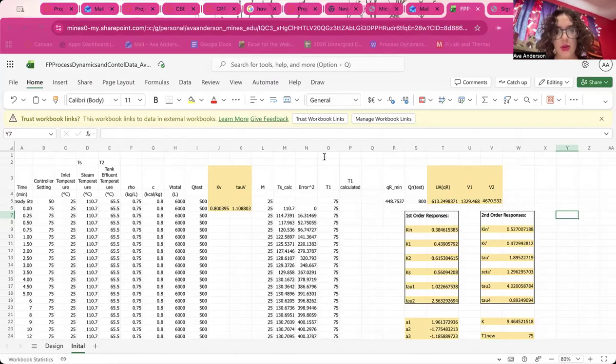The controller design was performed with Simulink. KC was found using a gain block in place of GC of S, and I manipulated the gain to see when constant oscillations were achieved. I'll show that in a second as well. The gain input became GC max, the value that I was putting in the gain block, that ended up being KC max. And PU is the period of those oscillations found, which ended up being 3.81 seconds, and the corresponding omega U was found to be 1.65 radians per minute.